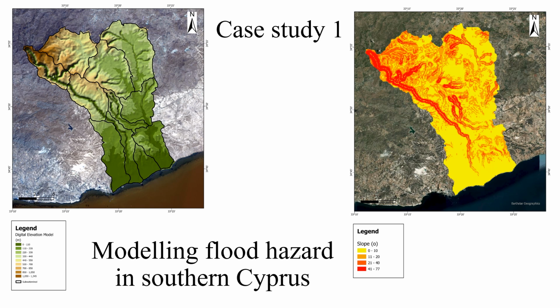We used, of course, the DEM, which you can see here on your left, to generate the slope which is shown to your right. It is very clear that almost the entire lower areas, as well as a large part in the upper reaches to the northeast of the study area, are nearly flat, with inclinations of less than 10 degrees. These areas are particularly prone to flooding, regardless of whether the drainage network is well or poorly developed.